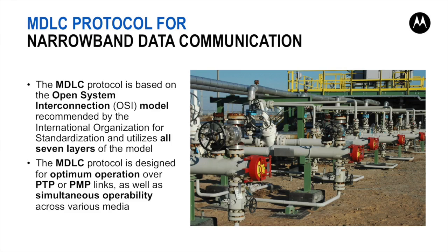The MDLC supports multiple logical channels per RTU physical communication port, enabling simultaneous central-to-RTU and RTU-to-RTU sessions. It also enables each RTU to simultaneously run several kinds of communication, such as reporting alarms by contention, online monitoring, performing extensive diagnostics checks, etc.